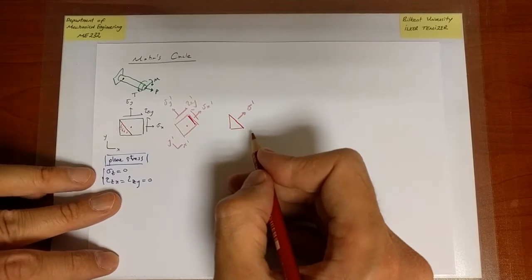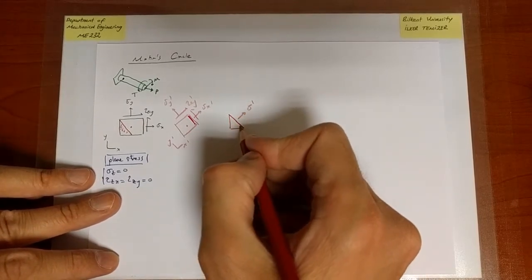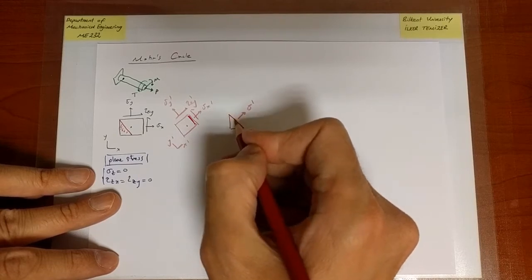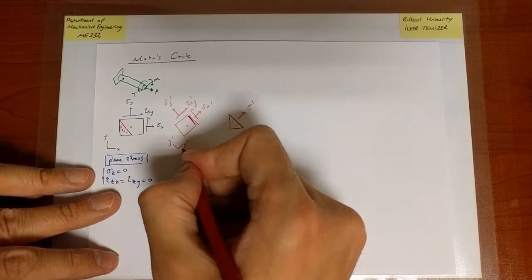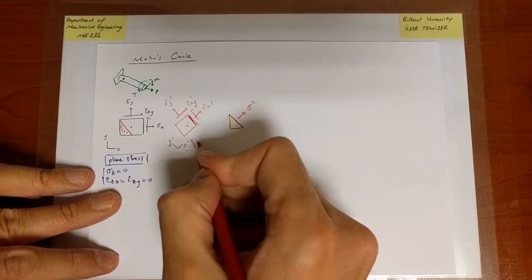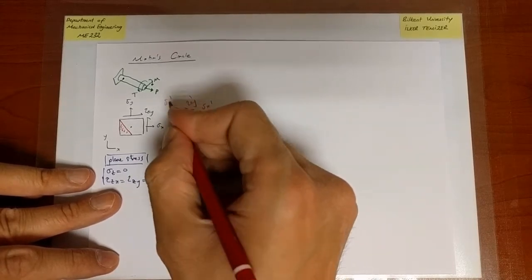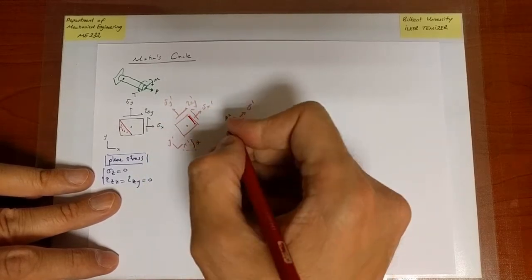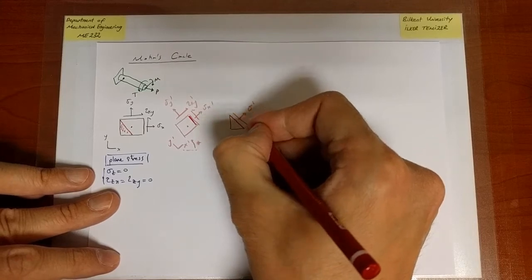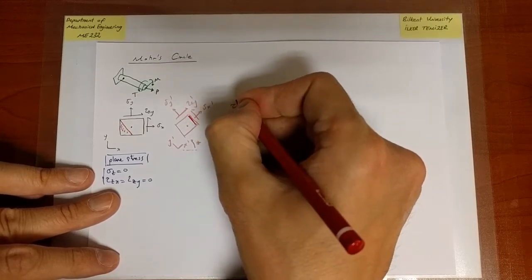It's not necessarily x, because if I choose not this plane but a plane with orientation theta plus pi over 2, where the orientation theta is arbitrary, it would send me to that plane, which is sigma y prime. So I'm just going to put sigma prime, and I understand that there is only one shear stress we're talking about. Let me just call it tau prime.